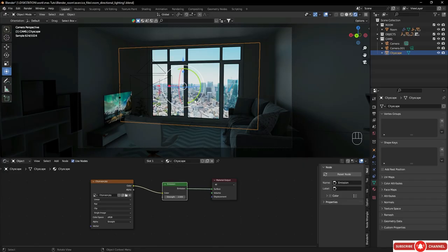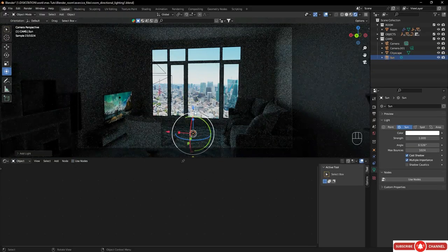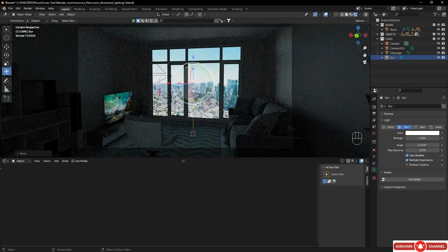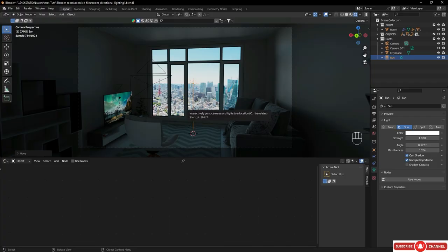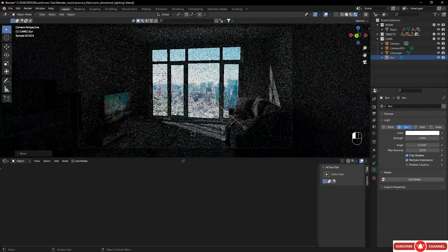direction light. Okay, so what I'm going to do is to shift right click here to spot our 3D cursor. Then we're going to Shift A and add a light, a sunlight. Okay, this sunlight is going to light the scene. The location of the light is of no importance, but now if I move it something like here, so it's inside the scene, we have this yellow dot. Let's switch here to make it more obvious. We have this yellow dot. If I just move it this way, you can see I can orient the light the way I want.